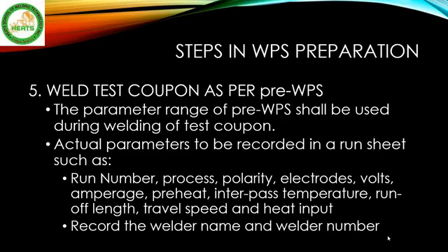Okay, the parameter range of the pre-WPS shall be used during welding of the test coupon. No other. You need to use the pre-written pre-WPS. The actual parameters are to be recorded in a run sheet.